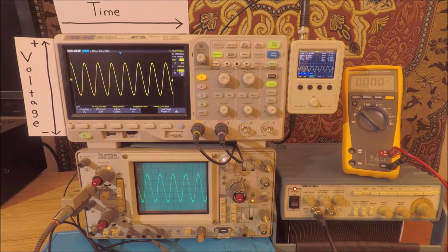I mentioned that these are three very different oscilloscopes, so let's talk about some of those differences. Starting with the analog oscilloscope in the bottom here, I mentioned that it does have a lot of buttons and switches, which will allow us to change how the waveform is displayed on the CRT. But one thing it doesn't have is a way to display text. So if we're going to read things like wavelength and frequency and voltages, it won't give us an explicit readout the same way that a voltmeter would.